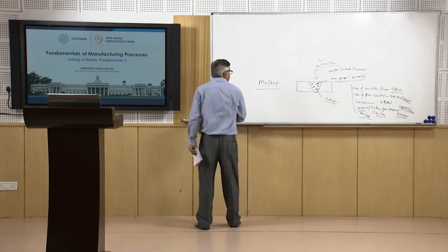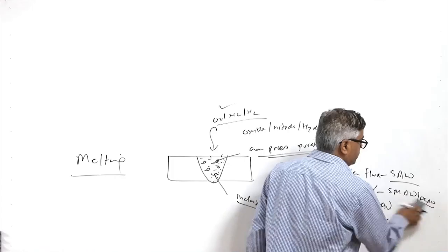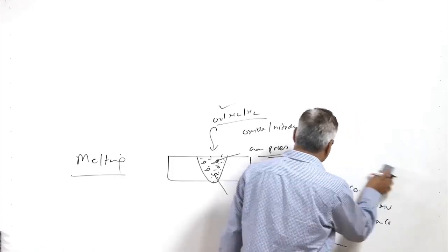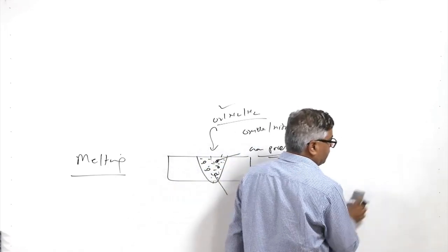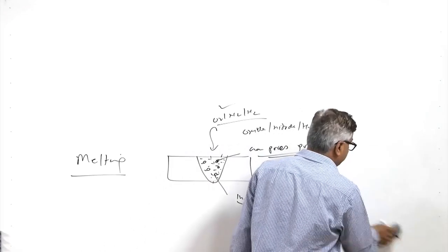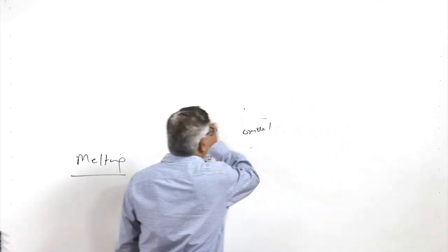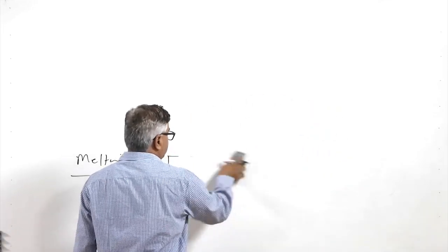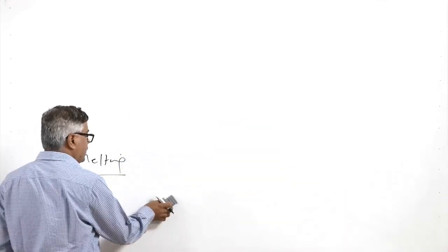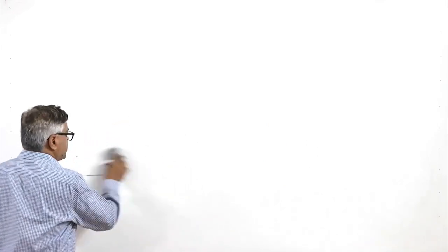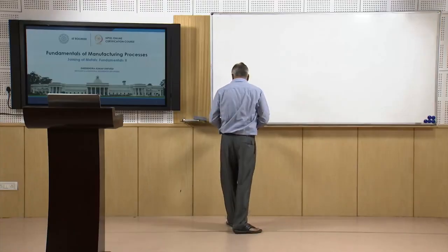Also the availability of helium becomes an issue, because it is not that easily available, and the cost difference is huge, like maybe 4 to 5 times cost difference between argon and helium. So, for most of the commercial purposes like the welding of pressure vessels, where reasonably good quality welds are required, argon is used as a shielding gas, while helium is preferred for very high quality weld joints, because it is very costly and very high flow rates are needed when helium is used.